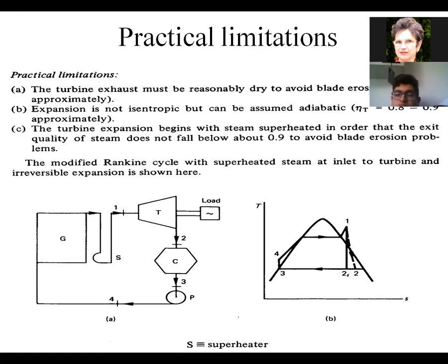Is it clear? So it is a benefit for the turbine because the turbine is put into movement by the energy of the vapors, yes? At the beginning, they are only vapors, but up to here, they start to be mixed with water. And this water generates a mechanical erosion on the blades. And the less liquid you have, the much better. So situation 2 is better for the turbine. You have to remember this.